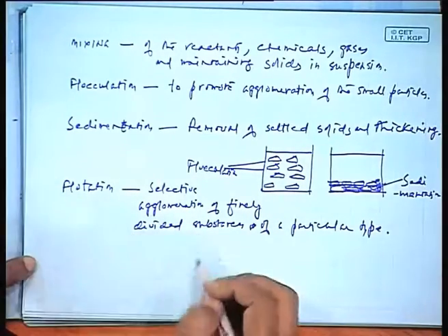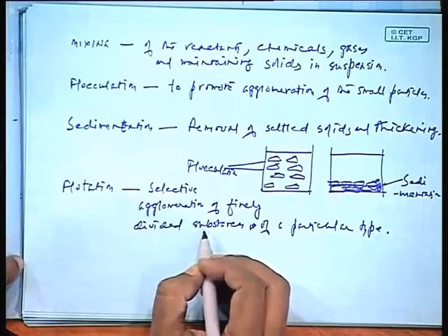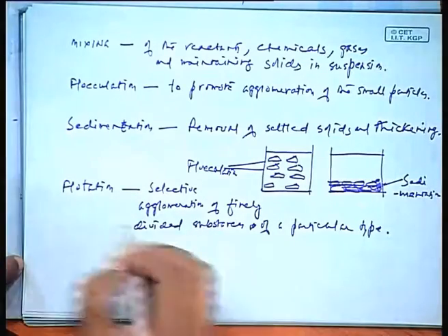If you remember, flotation is what happens in the flotation chamber. In all cases it would generally try to attach some selected particles. This is very common in mining and concentration processes, in froth flotation. What we generally do in froth flotation is use a particular organic or metal organic substance, say sodium xanthate or potassium xanthate. Particularly in a copper concentration process, it would only agglomerate with the copper particles and bring them up to the surface. This is the flotation part.